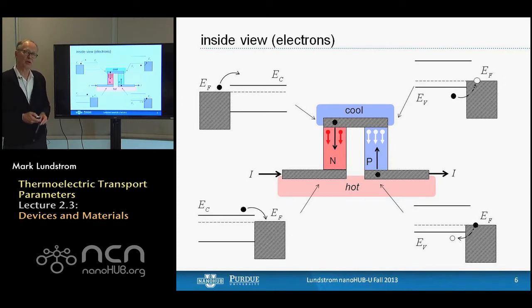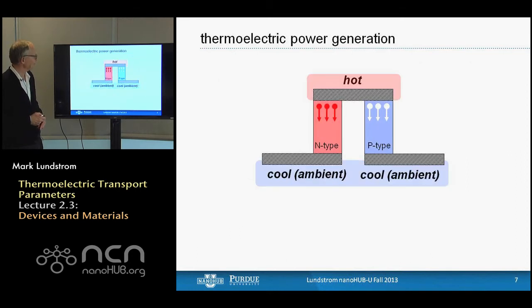And then electrons flow down to the bottom of the N-leg. When they get to the metal contact, they lower their energy and drop down near the Fermi energy in the metal. That releases heat, and that's the Peltier heating at the bottom plate. So that's an equivalent view of how this Peltier cooler works, all in terms of electron flow.